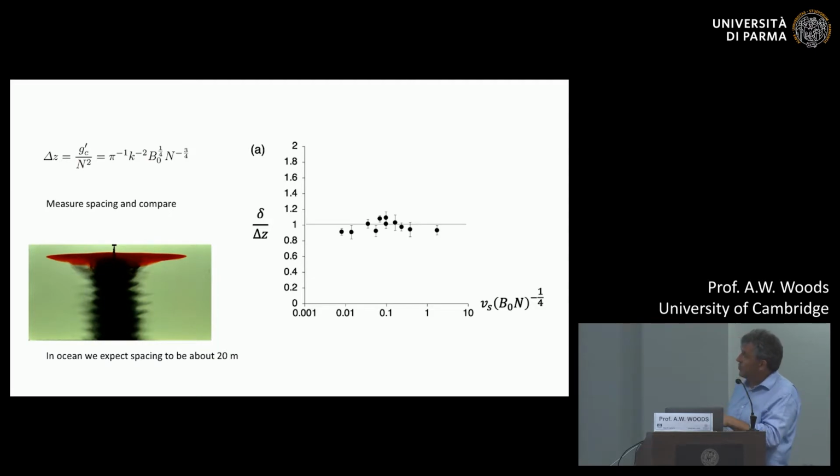So one question is, what are these ripples? What's going on with all these ripples on the edge of the structure? Well, if you think very simply about this, we have a column here of particles sedimenting through a stratified layer of water. So the density here is a little bit bigger than the density there because there's some particles present in the fluid. And that tries to make this fluid convect downwards a bit relative to the surrounding fluid. But if the fluid starts moving down, it then remembers there's stratification out here, and so it can't go very far, and it needs to stop, and so it spreads out.